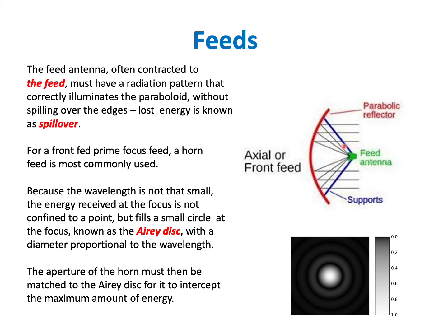Now, if we put a feed right at the focus, that's known as a prime focus feed. And generally, we use a horn feed for that. So we'll get to horn feeds at the end of this lecture.